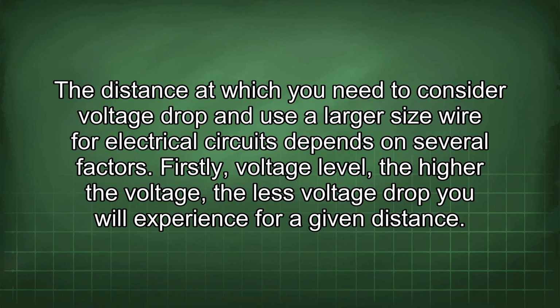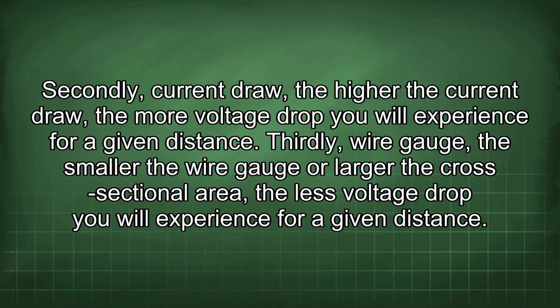The distance at which you need to consider voltage drop and use a larger size wire for electrical circuits depends on several factors. Firstly, voltage level. The higher the voltage, the less voltage drop you will experience for a given distance. Secondly, current draw. The higher the current draw, the more voltage drop you will experience for a given distance.